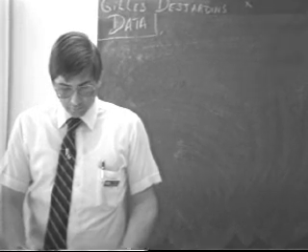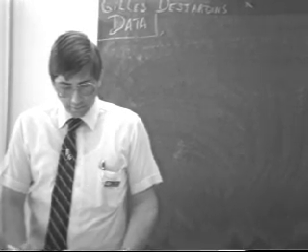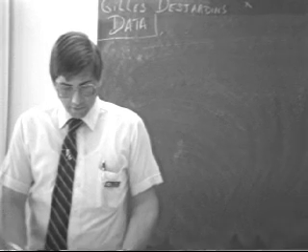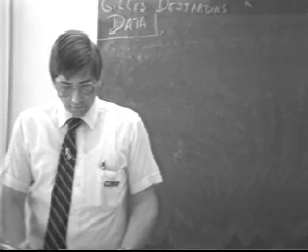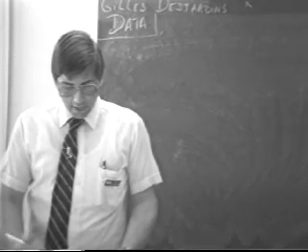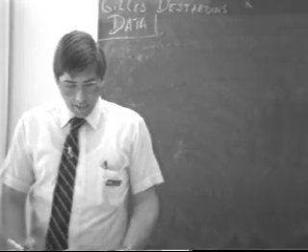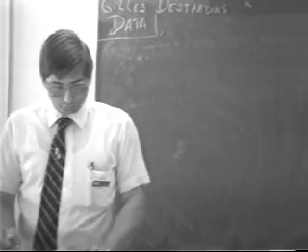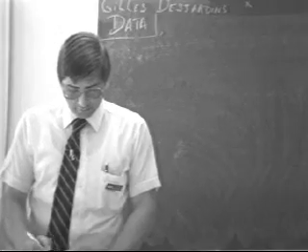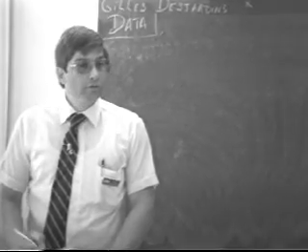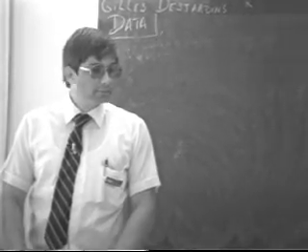Next page 7, reads table 3, latches sample in DAC 3, reads table 4, latches sample in DAC 4, increments lookup table, and goes back to 2, which is page 6. Now I will do this as long as it's on test.